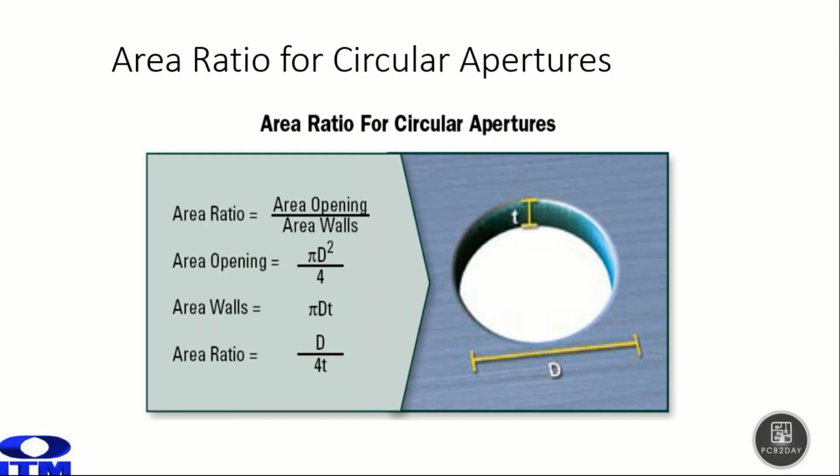You can see that the thicker the stencil we go, the more likely we're going to meet that area ratio, whereas if we go too thin a stencil, we may violate it. When we violate it, we get what we call a too tall and thin aperture. In other words, we're not meeting that ratio because our thickness isn't enough, assuming we've done the geometry in length and width, or in this case diameter. And what happens is it just doesn't release properly. So here's an example.